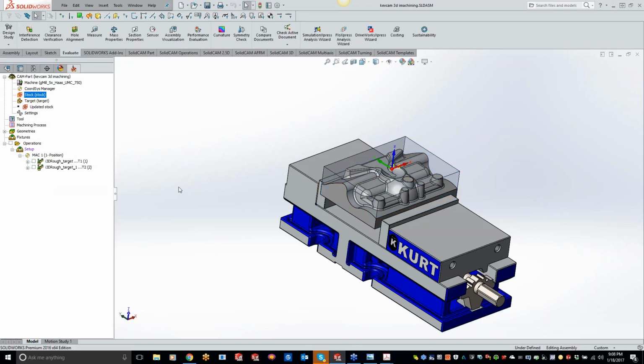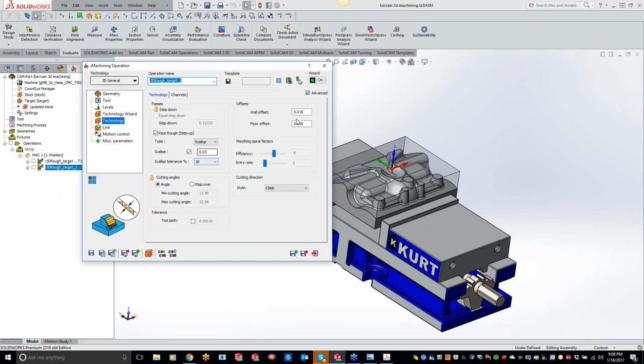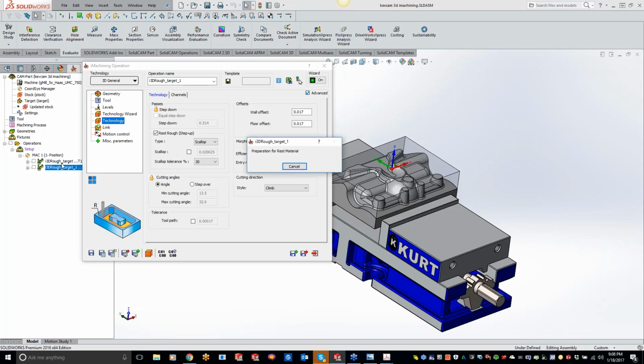Now, technically, on this particular one, if I change this to, let's just do a 17 thou, and 17, and I'm going to turn off this so it calculates a little faster, it shouldn't break what's up above. What I mean by breaking, or what he's talking about there, is you'll get the little asterisk mark, or the little star, and it's just asking you to recalculate it. So something has changed very minutely, and it's wanting to pull that data back in.